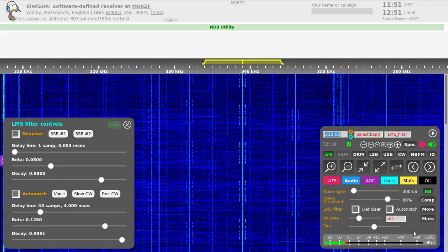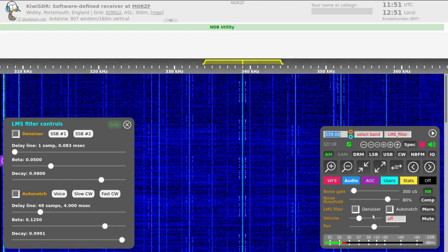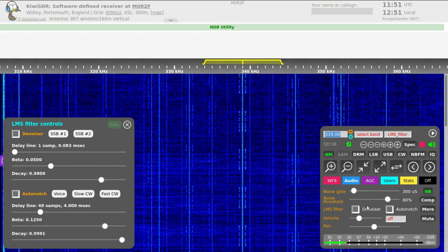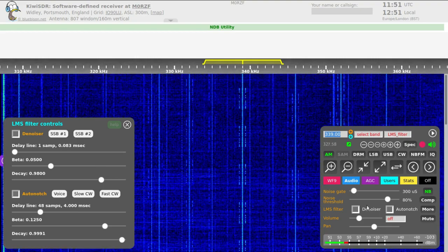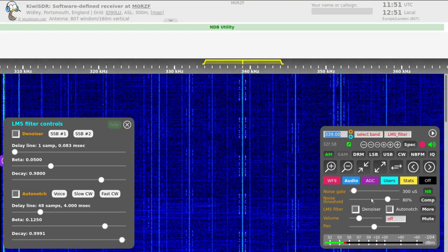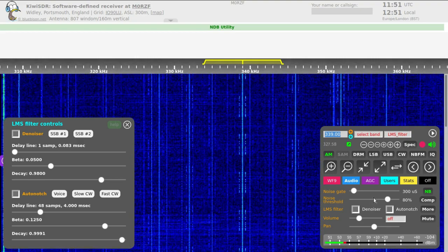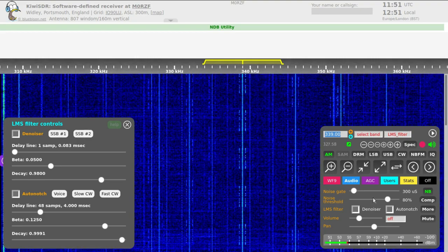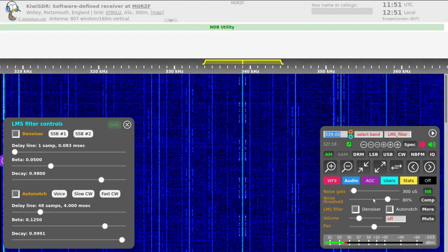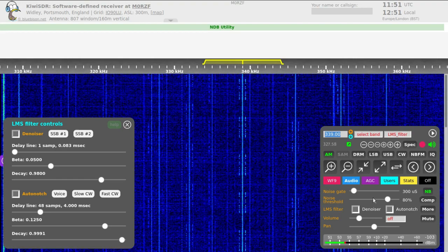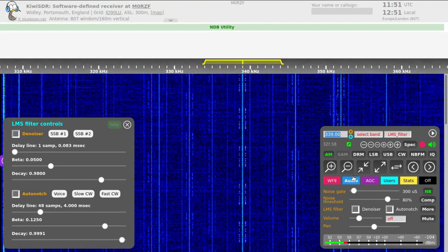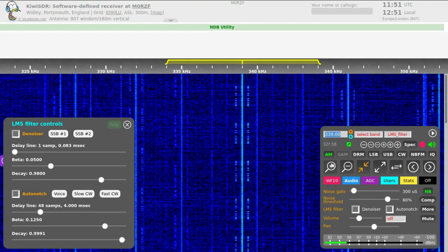There are still some more changes we can make to improve reception. The filtered passband is pretty wide. Notice that the Morse identification is quite low in frequency. What is it, 800 hertz or so? I have forgotten the specification for non-directional beacons in the UK. It's a lower pitch than is used in the US. But we can close in a bit.